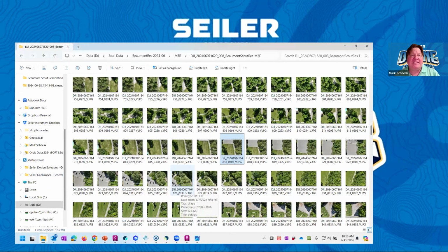There are some websites that allow you to really read into the EXIF data of these photos, and you'll see things like the drone IMU data: not only its position in the sky, but its pitch, roll, and yaw axis at the time the photo was taken. Different photogrammetry software can take advantage of not only the camera tilts, but the rotation of the drone, to get not only accurate position in X, Y, and Z, but also the right rotation orientation. And all this software could take advantage of that.